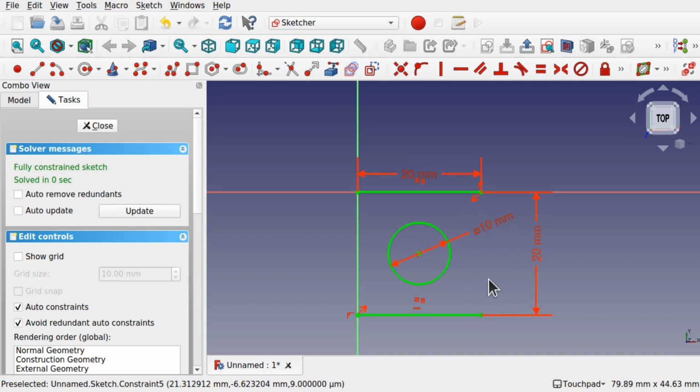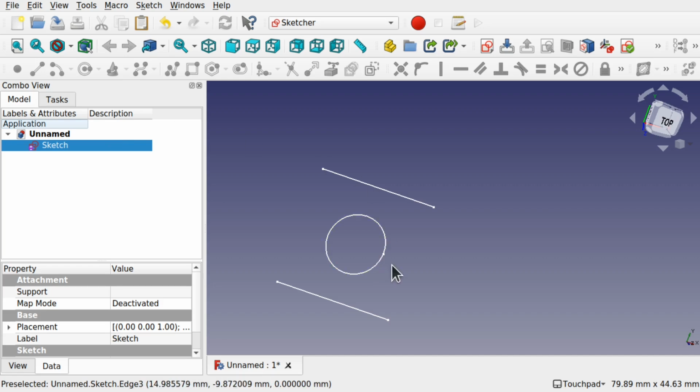The reason why this is important, because we need to close this sketch up when we repeat. So this pattern here will repeat it to the right or to the left, and they will overlay these points and be coincident to them, but they won't be connected, and we'll connect those up in a moment. Also, we're going to add the beginning and the end lines for the beginning and the end of the repeats. Let's hit close, and we'll deal with the repeat of this sketch first.